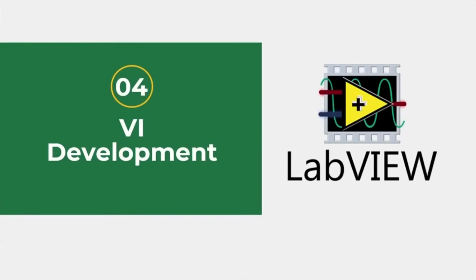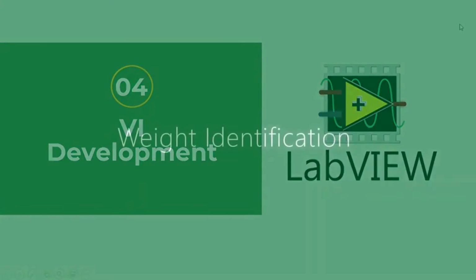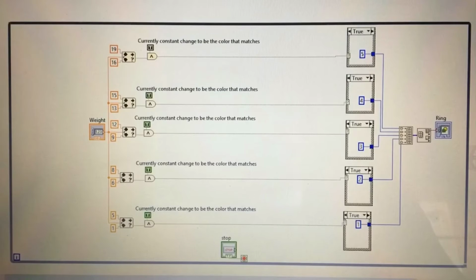Now moving on to VI development. I started off by developing a program to identify pills by weight. So there's an input for the weight, which in this image is a custom control. If this were a real system, we would use a strain gauge to send weight information, and we would run it through a series of calculations to figure out the weight of the pill. But since we're doing this virtually, it's just easier to use a custom weight or a random number generator.